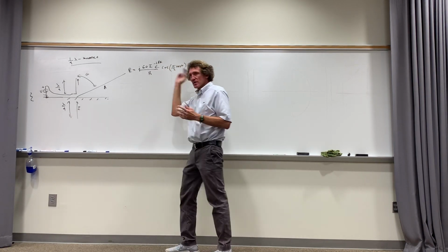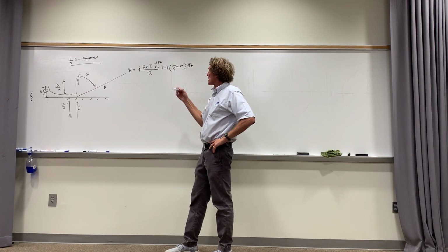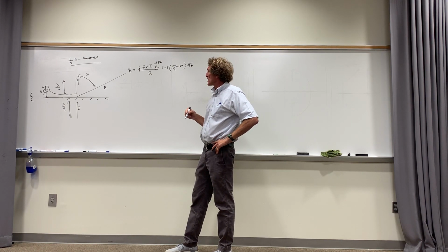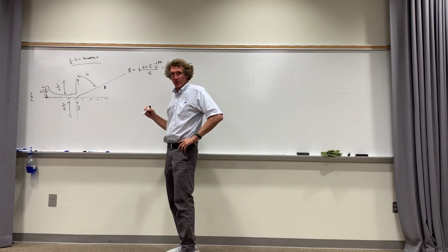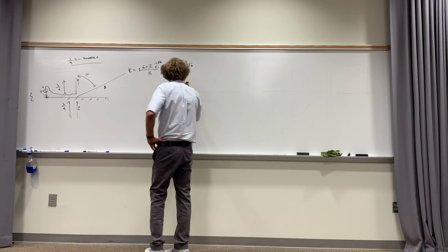Do y'all remember this is the equation for the fields from a half-wave dipole? It has that cosine of pi over 2 cosine of theta argument in there, and it's got j 60 I over r e to the minus j beta r. Correct, class? I don't know if he says that explicitly, but that's what it is. Now, if that's the electric field, it's still the same electric field from the monopole if it's a quarter wave. Got it? Keep going. What does that also mean?